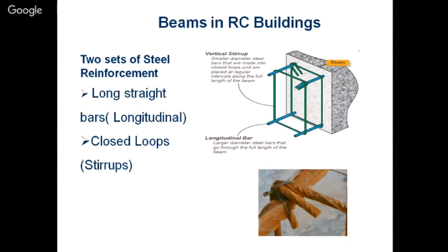So there are some specifications we require to keep things in control. There are small things we are required to keep in mind, like the hook where we are providing confining reinforcement. We are required to put it at 135 degrees, not at 90 degrees. If you draw a line parallel to your length, 90 plus 45 is 135 degrees, and the hooks should be bent inside, and they should not be left along the tie exactly at 90 degrees.